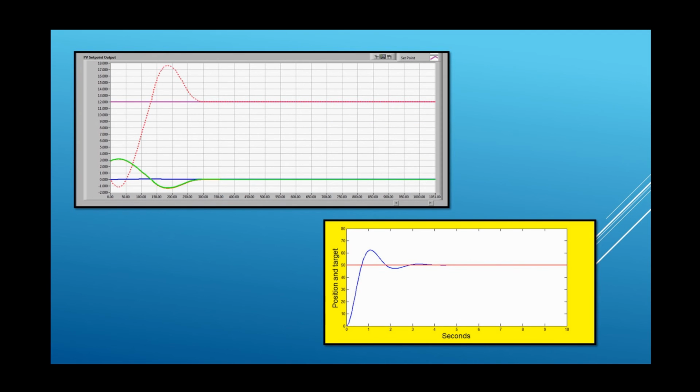Comparing the hardware experiment and the MATLAB simulation, the results of the influence of proportional gain and integral gain on the response are similar between hardware and simulation. The only difference is that there are some fluctuations after the response reaches the steady state gain in the MATLAB simulation, but they do not appear in the hardware experiment. I think this is because of the existence of friction force in the hardware experiment, which acts like a damper.